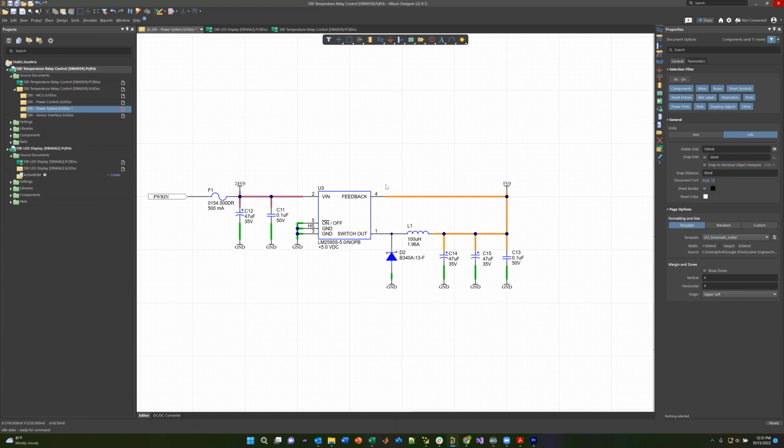It varies a little bit from project to project, but I use general color codes to represent the different voltages. So when I look at a printed page, as I print everything in color, it shows up really well. It just helps me diagnose and debug a board quickly, because I can look at this immediately and go, I've just got random power unknown coming in here on this power port, goes through a fuse, is nominally going to be 24 volts. That's what the client has requested. So that's why it says 24V0.